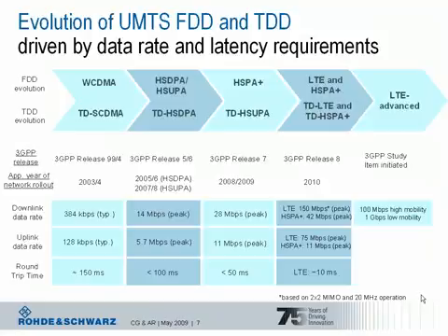but HSPA evolution does not stop yet. There is HSPA Plus with features in Release 7. HSPA Plus further enhances data rate in the downlink. Up to 28 megabit per second peak downlink data rate is possible by using, for example, MIMO multi-antenna technology and also higher order modulation schemes. In the uplink, by using 16 QAM modulation, 11 megabit per second peak uplink data rate is possible. Up to here, HSPA and HSPA Plus are all based on wideband CDMA 5 MHz operation.